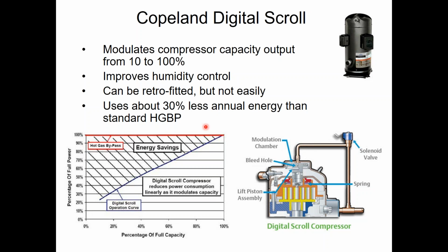This compressor is kind of unique in the way that it works. I believe Copeland is the only manufacturer of these, but they get used in all kinds of brands of equipment. And the way this guy unloads is he basically disables the scroll temporarily.